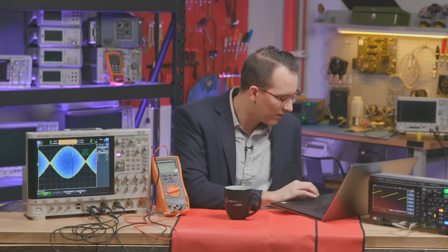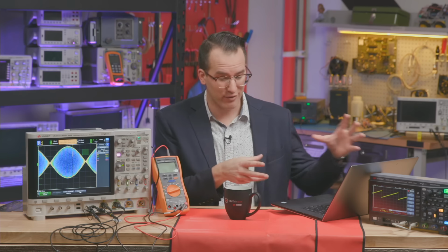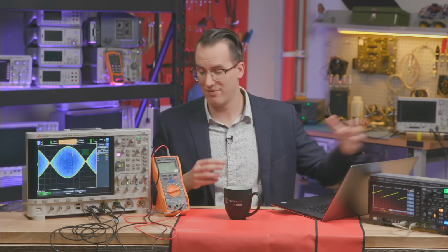Let's see. Can the scope be controlled through a PC, like using LabVIEW? Yes. All of the InfiniiVision scopes, most of the bench gear, I think every price option, has BenchView remote access. You can also use SCPI commands, and BenchView is now included complimentary with every scope, even the handheld ones. You get BenchView with that model or product's app for free. So if you already have Keysight gear, go check it out.